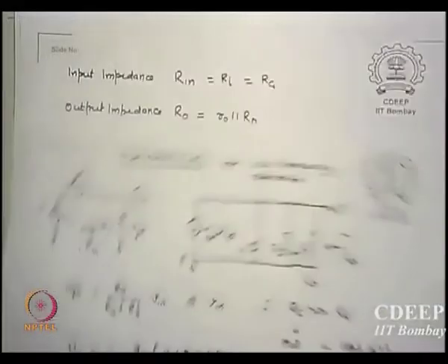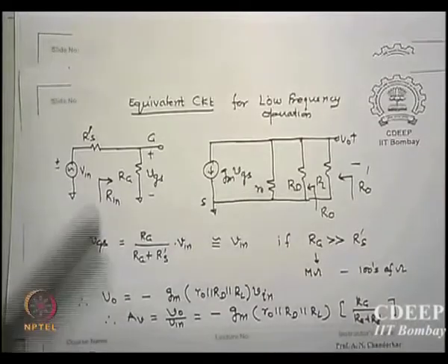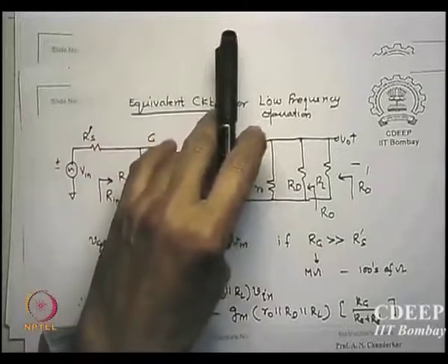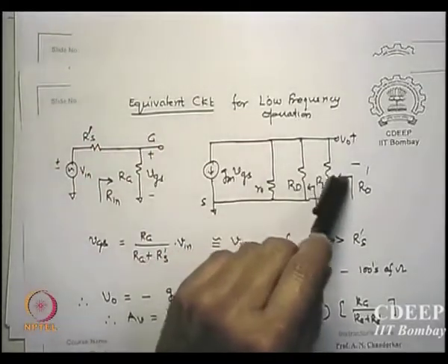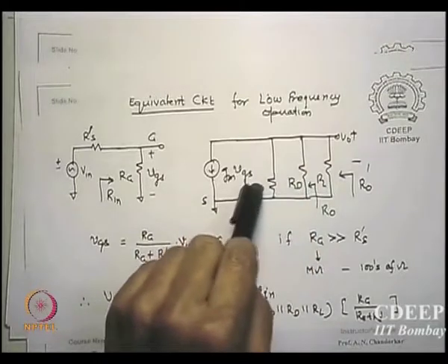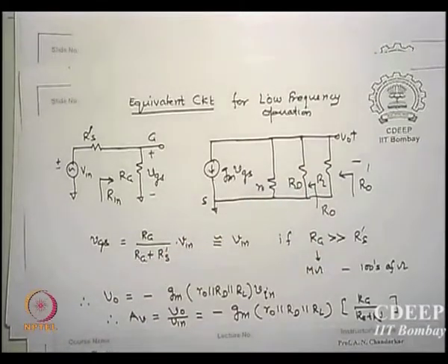What will be the output resistance seen again from here? By the same logic, short here, then the VGS is only coming from here. So what is the resistance that will be offered here? You open this, RD parallel R0, forget about RL.